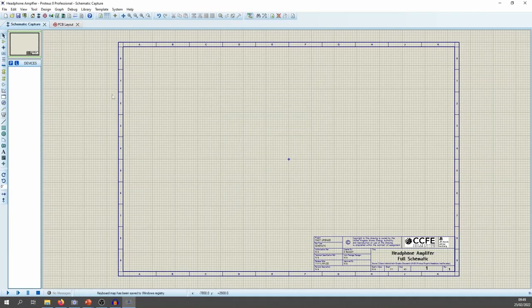The S and C, by the way, up here, can you see that? These 2 things? S and C switch between these 2 modes. I'm pressing S and C there. Selection is just if you want to move stuff around in your schematic. Component is when you want to place components and play around with them.